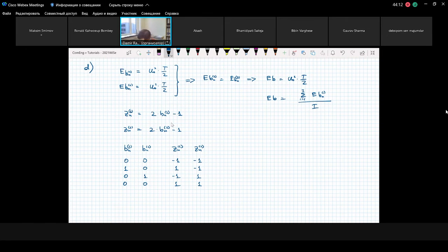Simply speaking, this part where we multiply by 2 and subtract 1 converts each bit from the range 0 to 1 to the range from -1 to 1. As a result, you see that each component has the same energy regardless of what we transmit, 1 or -1. But if you wouldn't have such a block, which maps 0 and 1 to -1 and 1, then you just follow the expression that I have below.